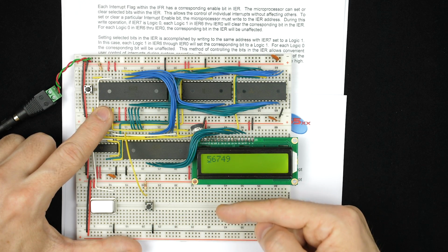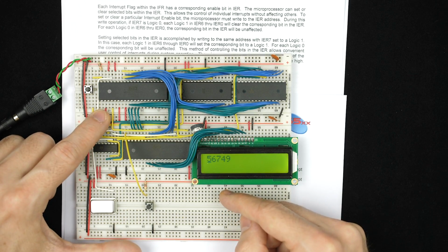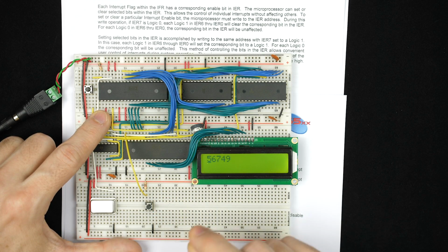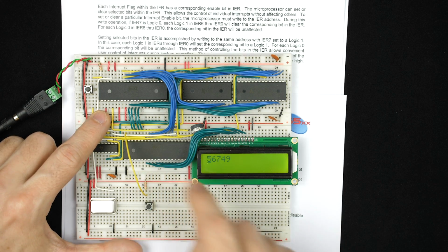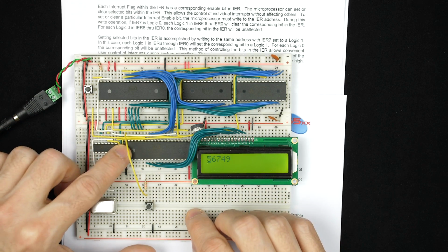And it would go back and increment the counter again and again and again, because essentially the interrupt was triggered anytime the button was depressed, not just at the moment where it transitioned low. So that's the thing that we're getting out of this, right? Because we have that ability to detect that low going edge and only fire the interrupt then.